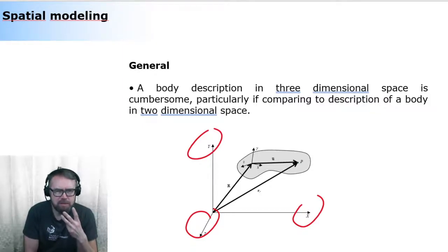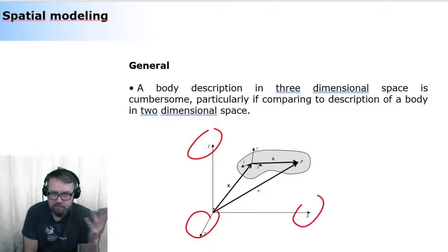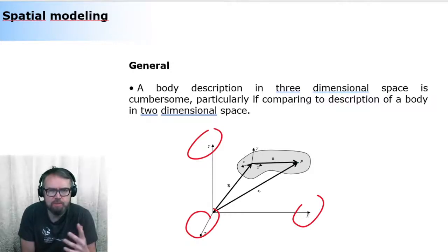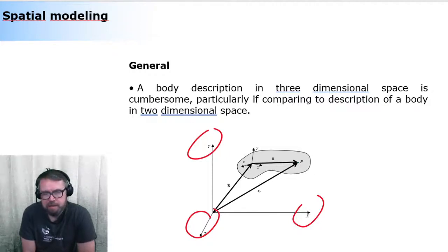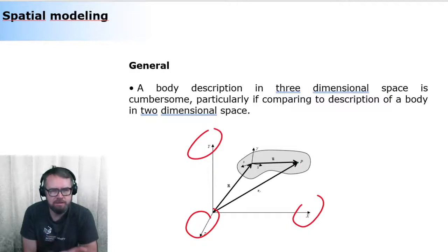There is always this possible configuration where these 3 rotations are no longer clear, and it is not clear what is what. And this is when you're reaching the singularity or locking configuration. You cannot differentiate what rotation is what. That's what can happen to you. And it's always a problem whenever using 3 parameters. So that's a big problem. And that already tells how much the rotation description is different in terms of planar and spatial case.